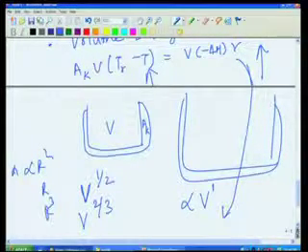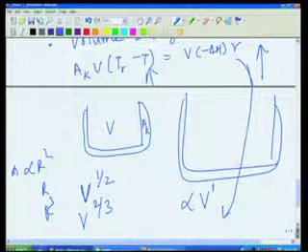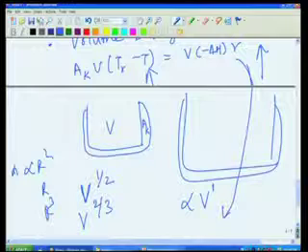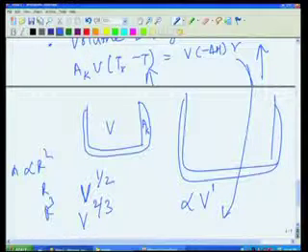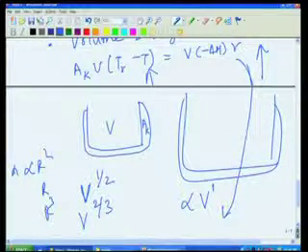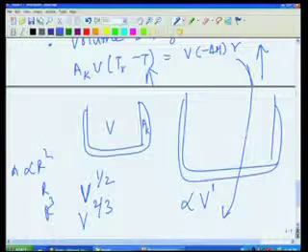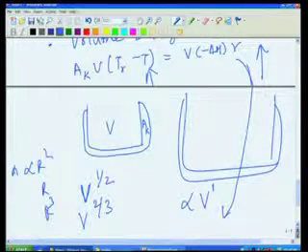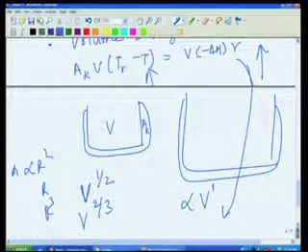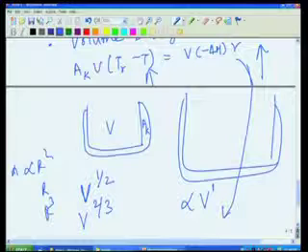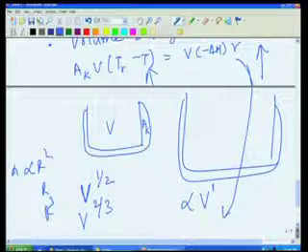As we go on increasing the reactor sizes, our cooling rate will be far lower compared to our heat generation rate, leading to a situation where heat removal is practically negligible compared to heat generation. Another scenario where adiabatic operation becomes important.